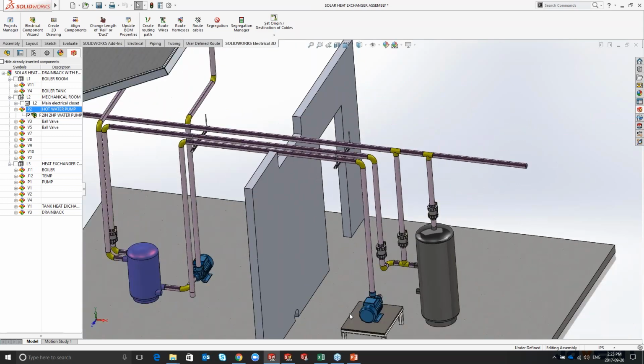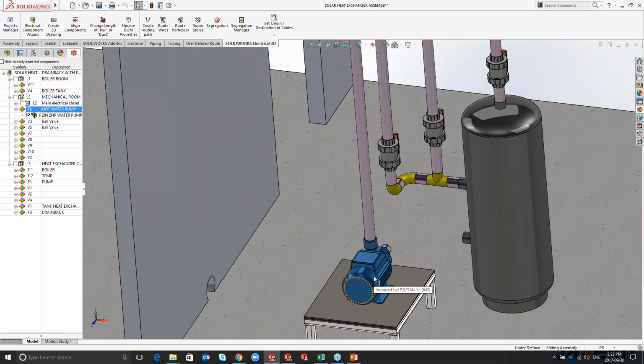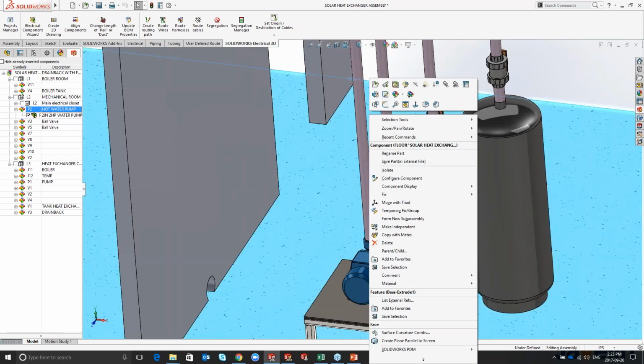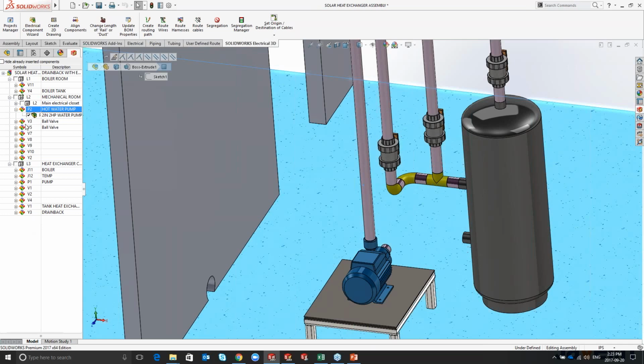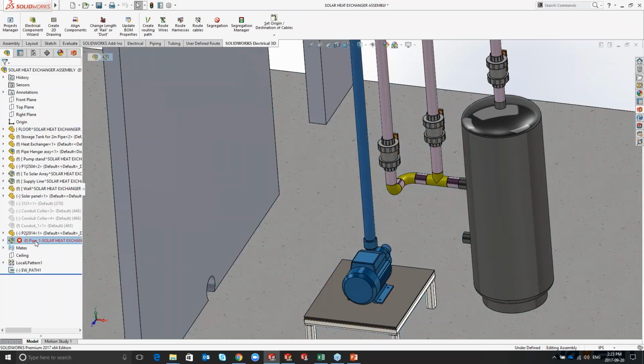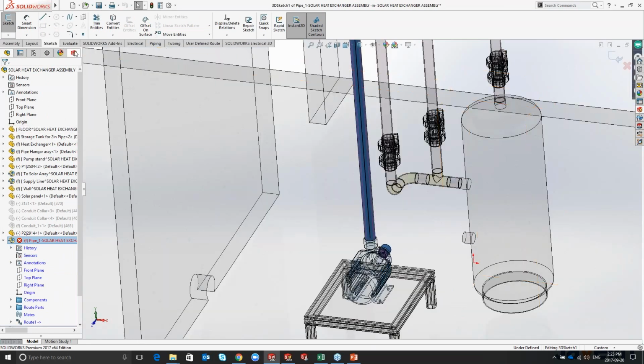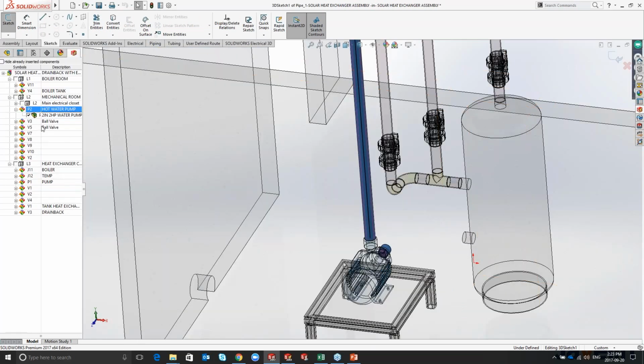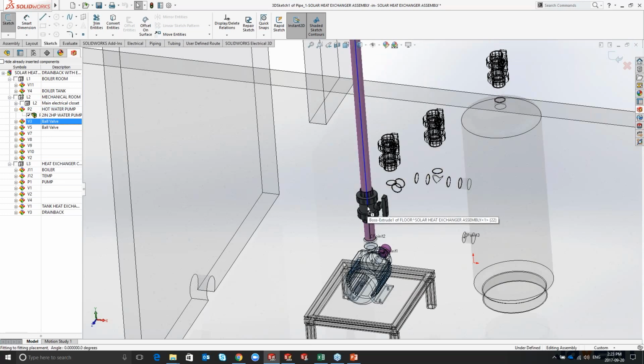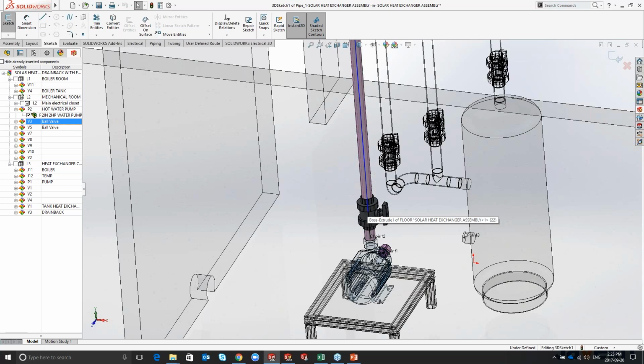And as you do that, you can also go ahead and insert other components. So in this case, let's say I right-click on this, and we're going to, that's right, it looks like I clicked on the entire plane. I'm going to right-click on the pipe, and we're going to edit this route. If we decide to edit this route, we can then also go ahead and insert the ball valve. To insert the ball valve, you simply have to let it snap onto the pipe, and that should be carried over.